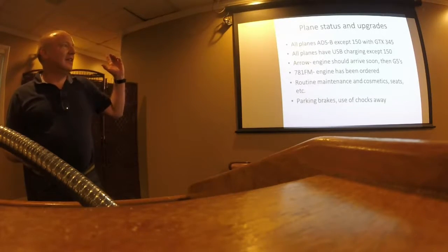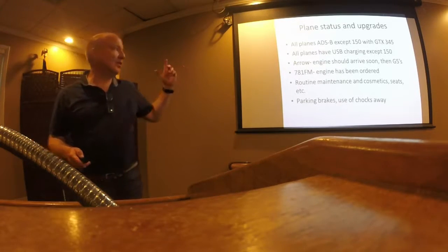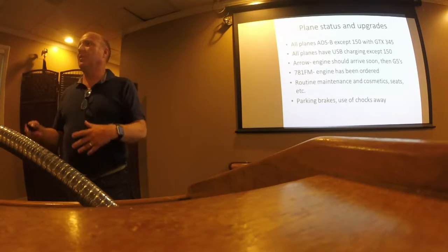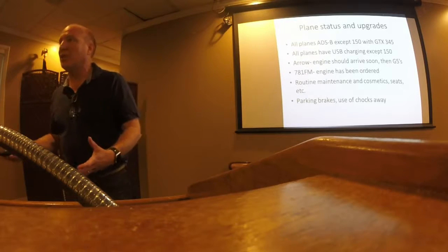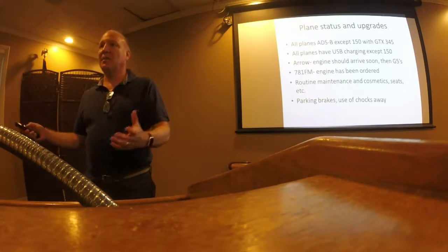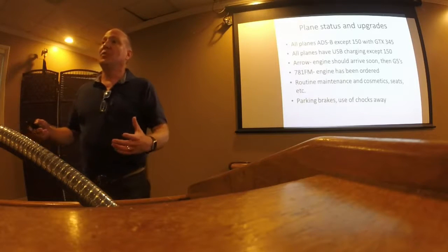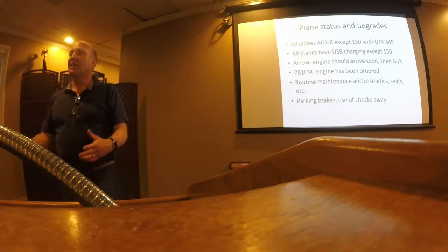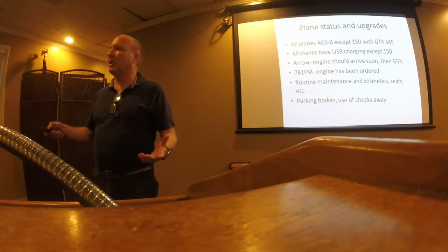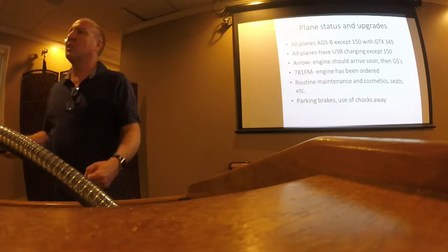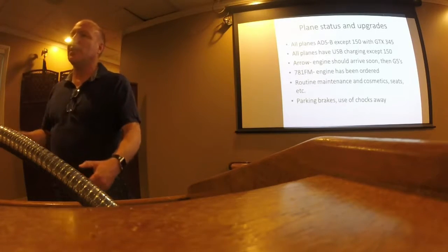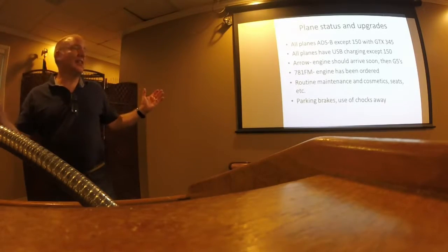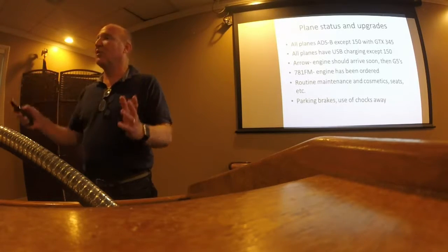So, parking brakes. If everybody recalls, back when Mike Grady was running the show, he encouraged us not to use the parking brakes unless you needed to. I'm not going to stand up here and say not to use them. You should be on the brakes with your feet regardless. Do not trust the parking brake. The issue you could potentially have, especially with the Arrow, is sometimes you can get some air in the line, and the brake might not disengage, and then you're stuck. So I'm not telling you not to use the parking brake, but definitely do not trust it.